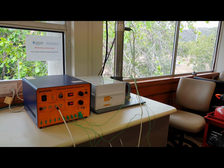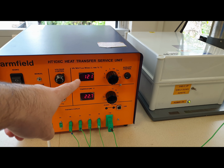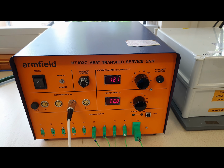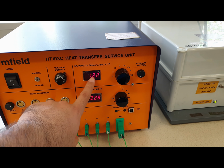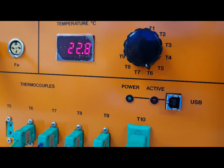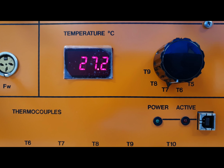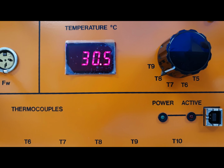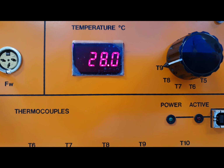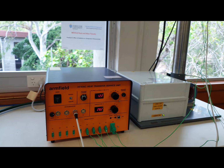Let me pause. Okay, 20 minutes passed and we almost have a steady temperature. Let's read the temperatures for case 3, in which we have no flow but we have the radiation effect. So T10 is going to be 122. Let's read the rest. T6 is 22.8, T7 27.2, T8 30.6, and T9 is 28. Okay, so this is case number 3, or test number 3.